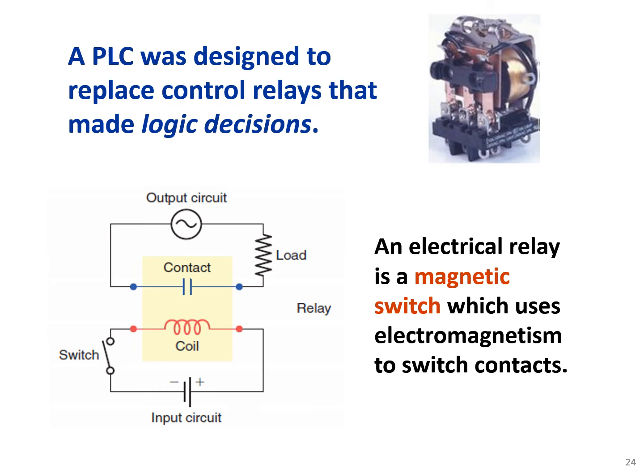Here we have an input circuit and we have an output circuit. When we close the input circuit, with the electromagnetic field between them, the contact will be closed and the circuit on the output module will be closed. So why do we use this? We usually use these types of circuits to operate only with low voltage DC to control or switch on and off a high voltage circuit.